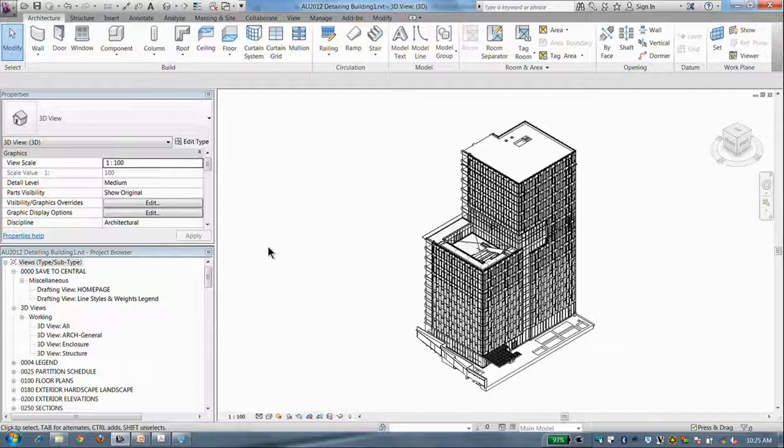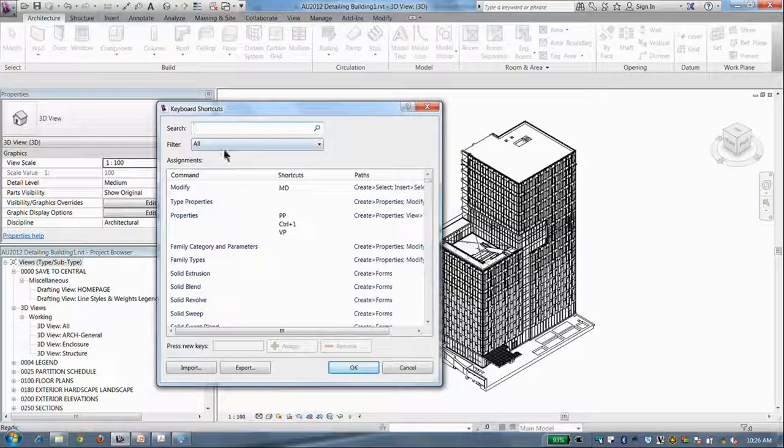What I've learned working with a lot of the architects who had been using CAD for many years, and their whole process of transitioning from that knowledge, their workflow, which is highly ingrained in what they do, into Revit, is working in an environment they're really familiar with. And fortunately, with Revit, keyboard shortcuts can actually mimic many of the things that are similar in CAD. So Revit may have a predefined list of keyboard shortcut information, and the keyboard shortcut for keyboard shortcuts is KS. So I'll point out things like this throughout, things that are on the edge of detailing, but are still very important to people's productivity.